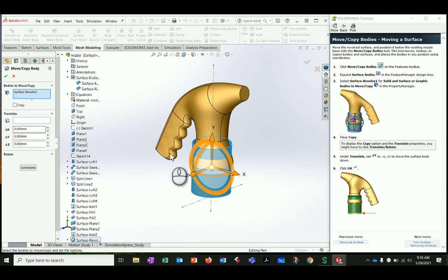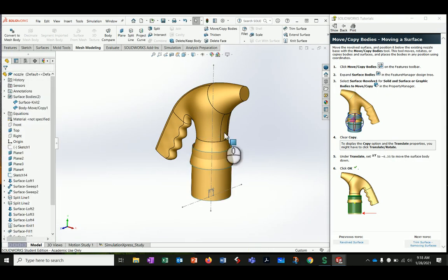And what it's saying is translate the Y there, minus 6.35. And it's important it's minus because we're going to move it down. Minus 6.35. Yep. And I'm going to say OK. And watch it, it'll just move down. There you go. And rebuilds itself.